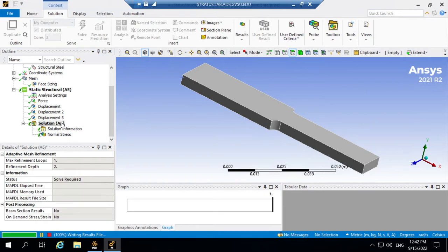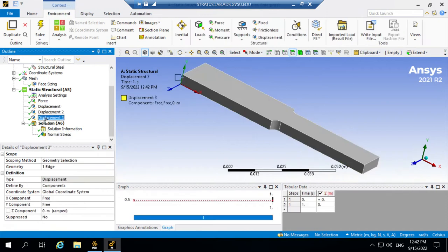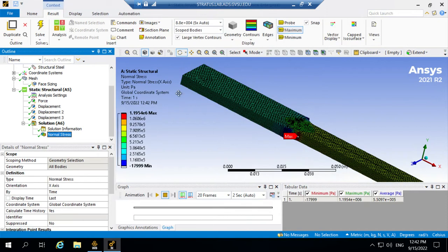Alright. Okay, yeah, you see this time the max is not happening at the end. It's happening here because, as I said, the new type of boundary condition I put relaxed stresses here, and my max went to a place that I was expecting. So that's a good thing. You see the results are quite stable now.